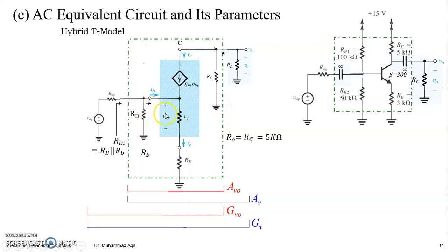It means whatever resistance is at the emitter in the T model is 1 plus beta times higher at the base, right? That's why R pi is equal to 1 plus beta times RE, right? So simple. You need to find out the total resistance at the emitter. So at the emitter we have this discrete RE connected as a circuit component, and that resistance is coming in series with this RE.